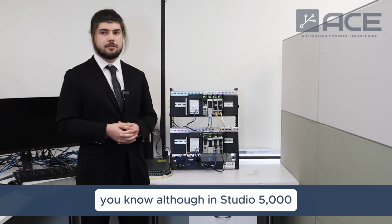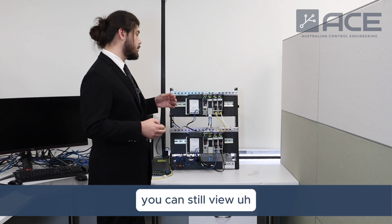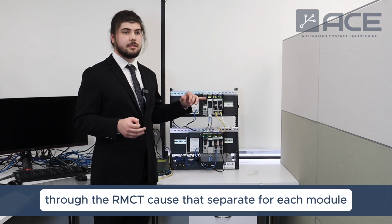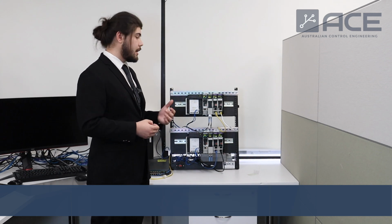Although in Studio 5000 you're connected to the primary in its run state, you can still view the status of the secondary and the primary through the RMCT, because that's separate for each module. Each module has its own RMCT, which is worth noting.